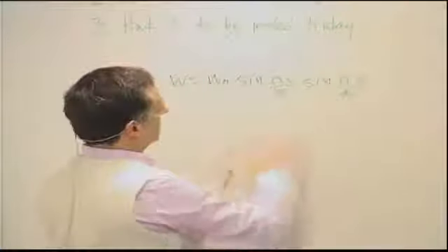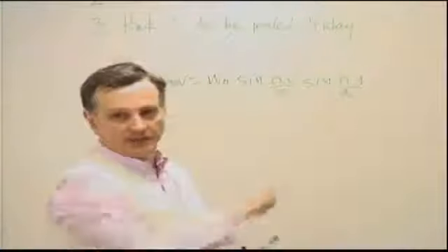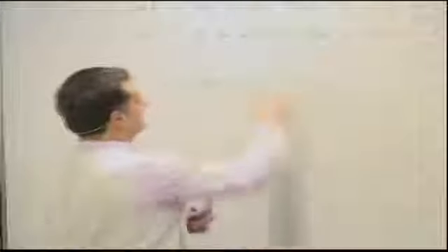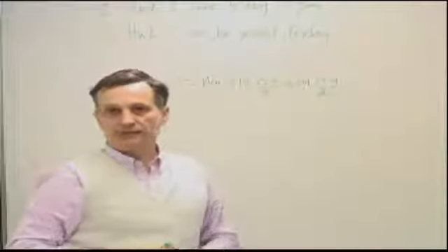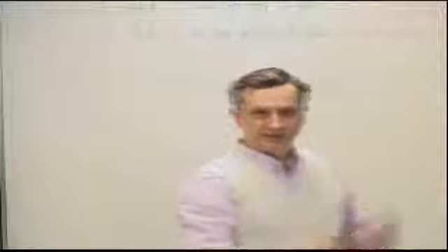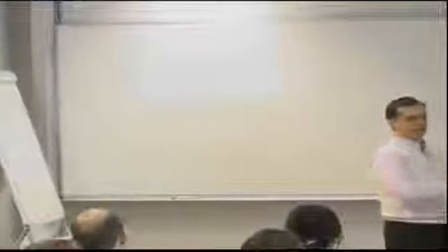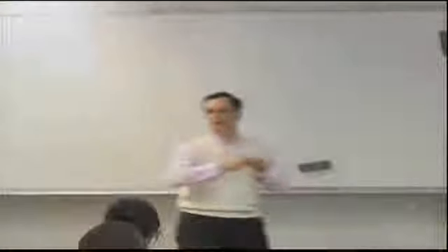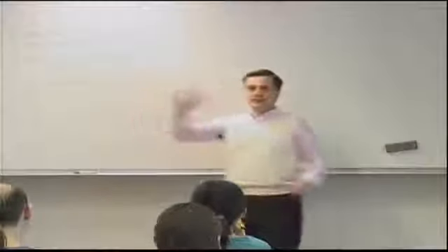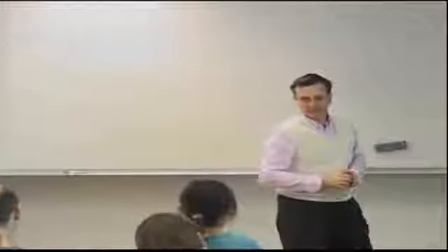If I, however, instead of A equals B, a square, had something that was significantly long, then this would not be sufficient. We would need more terms. If you remember when I was showing comparison from the results from that master's thesis a student was doing comparing to finite elements, when he did aspect ratios of 2 and 4 and so on, he had to not only change this value, but add many more terms. And then he found 2 and 3 half waves and so on.